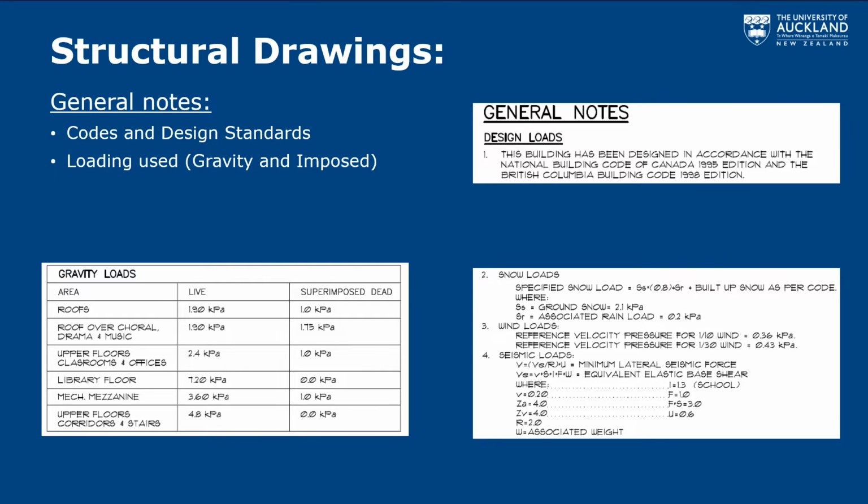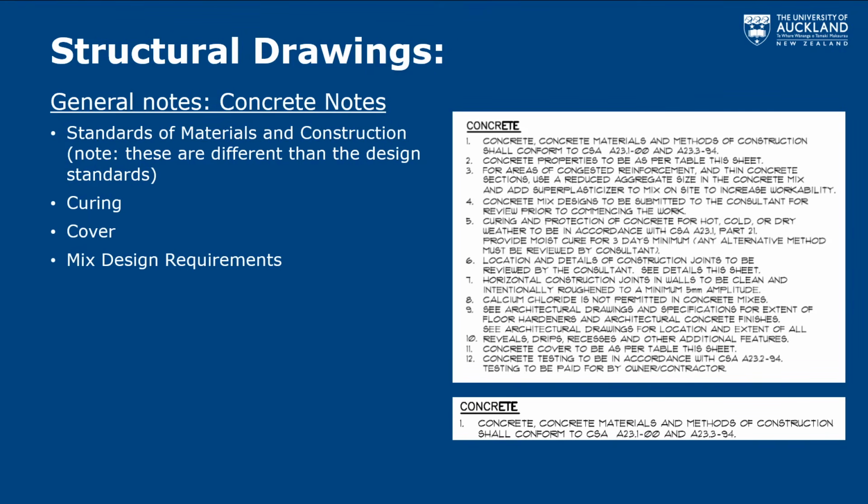Continue on to general notes. As I said, split this out into your different loadings, so for design loadings, your gravity and your wind loads. And then we'll start to go with some specific requirements for different materials. So almost every building has some concrete in it. Most foundations are typically concrete. There are some which are purely timber, purely steel, but many buildings utilize concrete at some stage within the construction. And so we need some overall important notes about how we're going to use concrete in this building.